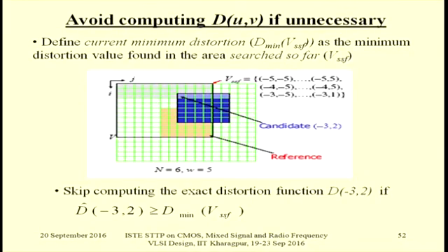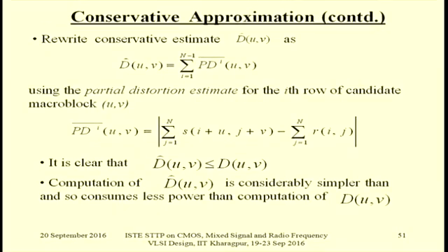So this is one example, but the detailed discussion will take a lot of time. In submicron technology, the leakage power, that is static power, is more dominant than the switching power we have discussed. In deep submicron technology, leakage power is more dominant. A lot of research is going on in reduction of leakage power. Earlier, the switching or dynamic component was the lion's share of the entire power. Nowadays, leakage power is gaining prevalence over switching power.